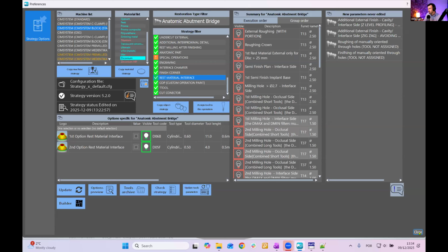And you mentioned the T tool, which I think is likely part of our answer for clearing that material at the 90-degree wall there. With the ball nose tool, of course, at the 90 degree, you can't get it. There's a little slanted material there. So you have to come in from the other side with a T-tool and clear all that.